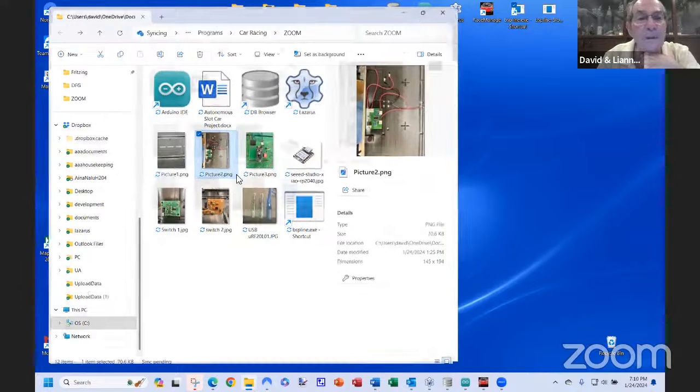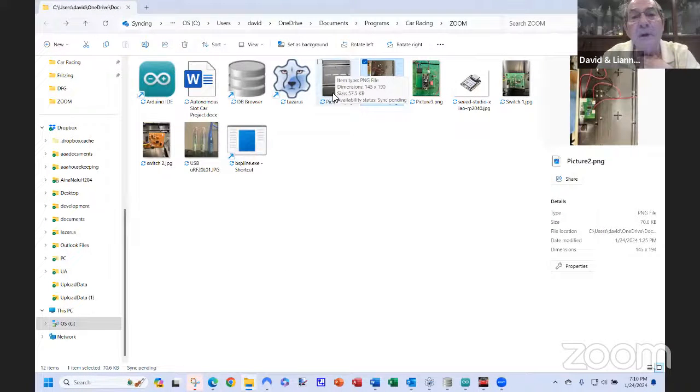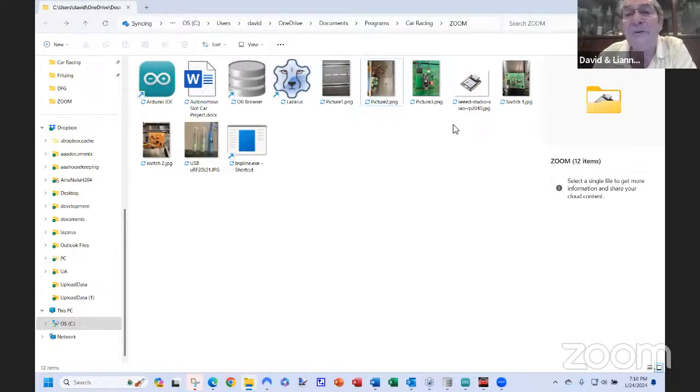So here's my track here. You may be able to see there's a little infrared light that I've put in on both of these. I don't know if it's clear to you out there. I connect that to a little board, sends the signal from there to what I call the gate microprocessor. So each gate, each trap has 2 infrared lights. When the car breaks the beam of those, and the IR lights read the signal from the car, the first piece of electronics sends that data to a gate microprocessor. The microprocessor can control up to 4 sets of gates, in other words, 8 lights. And then that microprocessor will send the data to my PC currently through radio Wi-Fi. It's not the greatest. I'm working on improving that, but it does work.